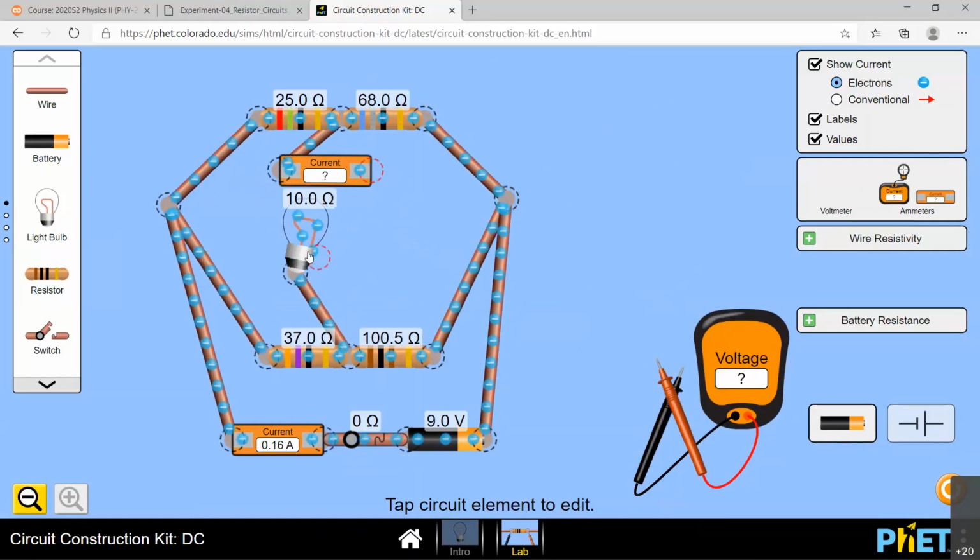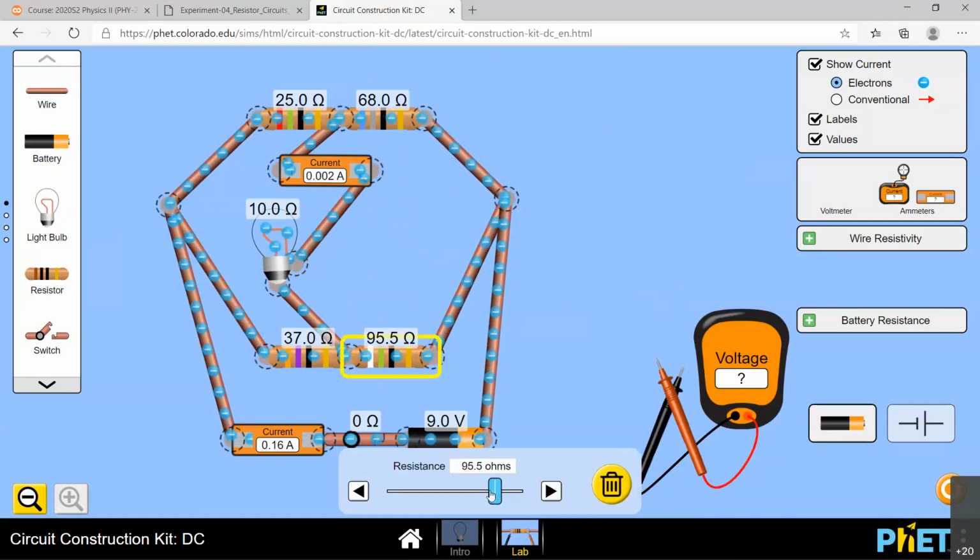I need more space here. All right, then let's bring another wire and then put the ammeter there. Okay. Now you can see if I change this resistance into a different number, you can see current passing through that line, right? And as a result of changing this resistance, at some point, the current passing through the midpoint will become 0. That's the exact point we need, okay? See, that number can be slightly different because current passing through there should show a 0 when it is very close to 100. Okay, 98 now.